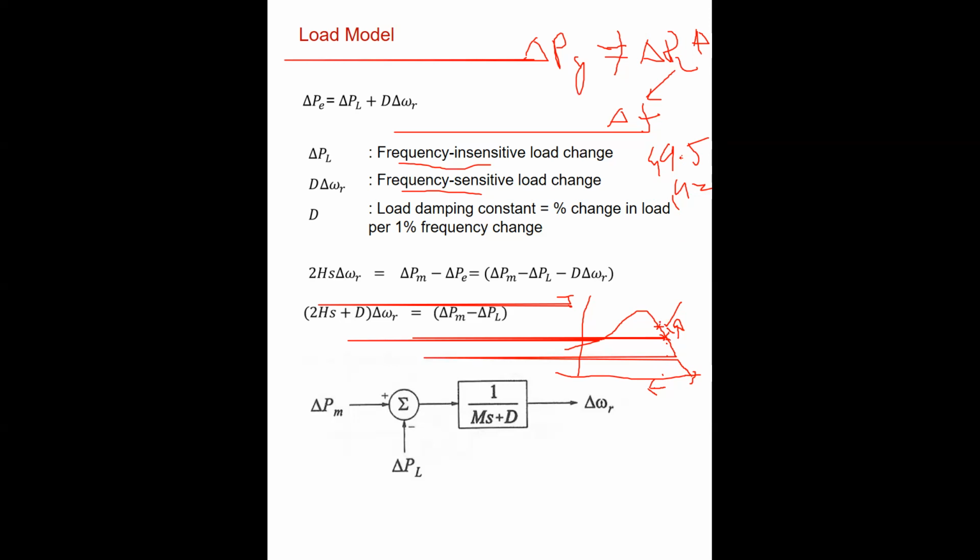But here the frequency has reduced, so the characteristic has moved to this one here now. So it's going to be a higher speed, right? No, this one will be lower speed basically, because this is synchronous speed 1500 RPM and this is 0 RPM here. So it is moving this side. So this is higher torque. That means higher torque is developed. So this higher torque means positive torque in the system,